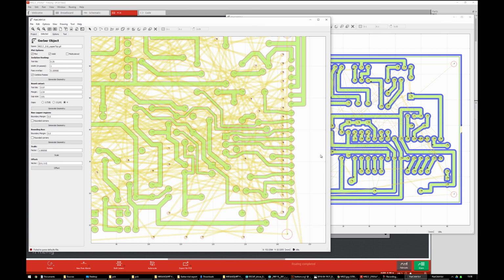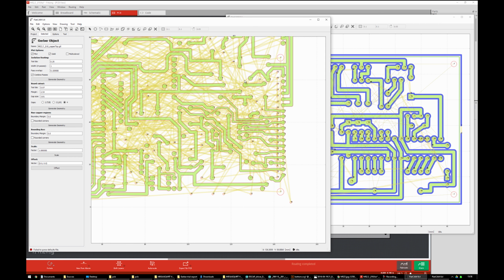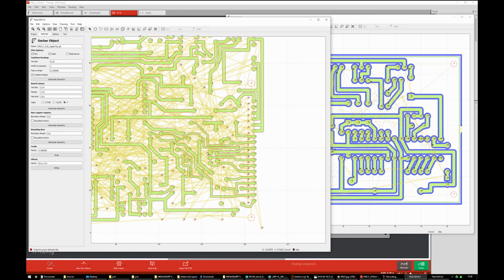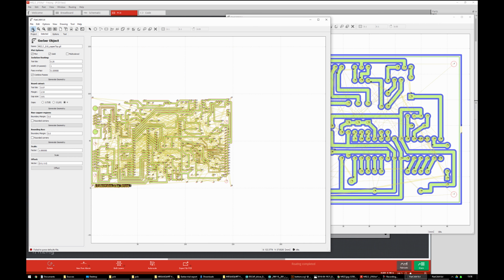Yeah, so we just need to make sure it leaves as much margin around your pads as possible, but it actually goes around every single one. So there aren't any joined up pads, which obviously will cause a short. So it's looking good, right? So I'm happy. Just gonna zoom to fit again.